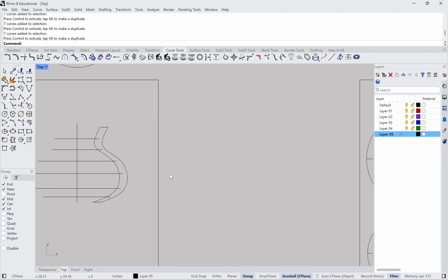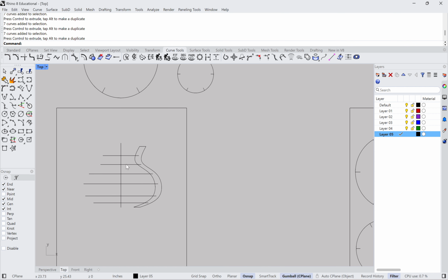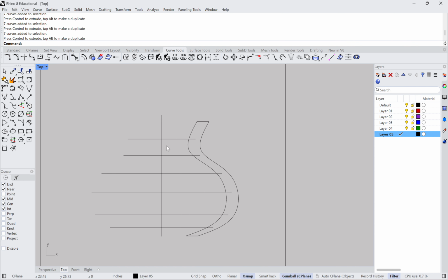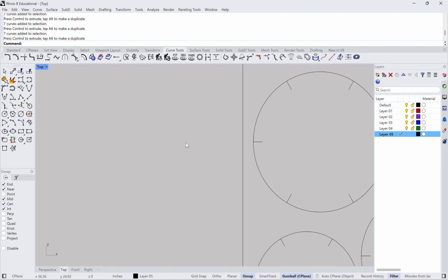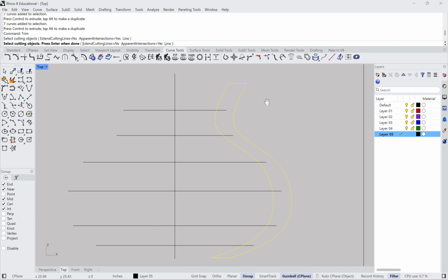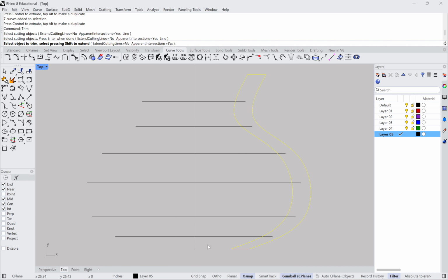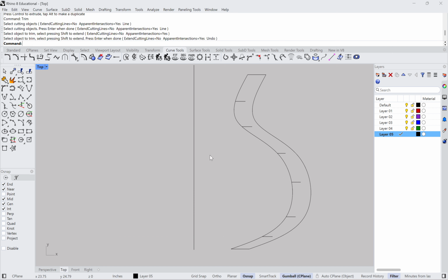But even as long as you've got a cut on the circular pieces of paper, you should be able to insert another piece perpendicularly into this one. So in this case, I'm going to try leaving these little cuts inside the profile shape. So I'll use the trim command, use the profile shape as my trimming object, and then get rid of everything on that side.